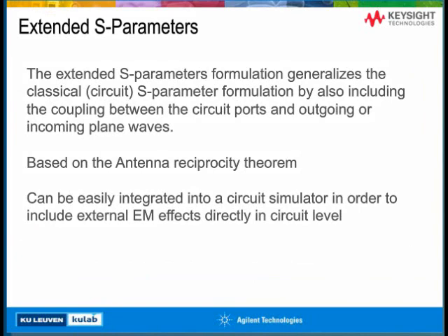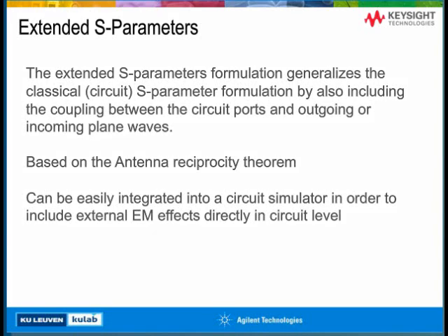So how did we use the reciprocity theorem in this example? We used it to extend the classical S-parameter formulation. So we introduced an extended S-parameter formulation which generalizes the classical circuit S-parameter formulation, also including the coupling between circuit ports and incoming or outgoing plane waves. It's again based on the reciprocity theorem, and because it's an S-parameter formulation, it can be easily introduced in circuit simulators to include external EMC effects directly at the circuit level. Because it's an S-parameter, it can also be attached quite easily to all kinds of circuitry.